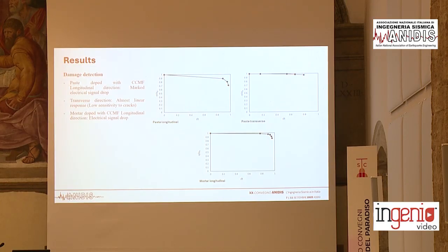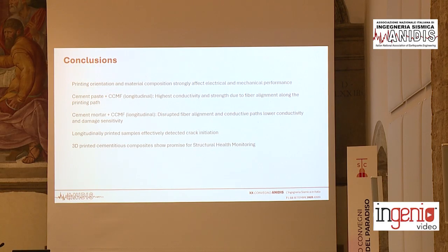And these results clearly show the trend in terms of the variation of the conductive parameter and also the mechanical parameter that relates the elasticity variation in each one of the cycles. And we can notice also that the direction of the fiber can clearly affect the response in this sense too, since we can now clearly see that a bigger drop is noticed for the samples both with the printing path following the long axis in the longitudinal direction. While in the perpendicular direction, this is not so clear, with almost linear behavior, let's say.